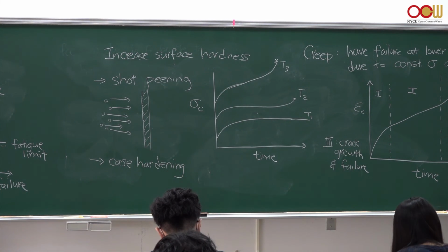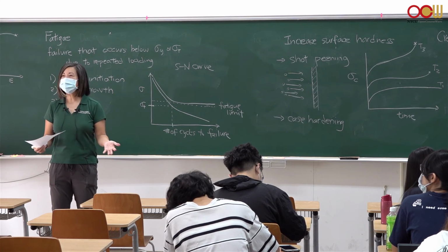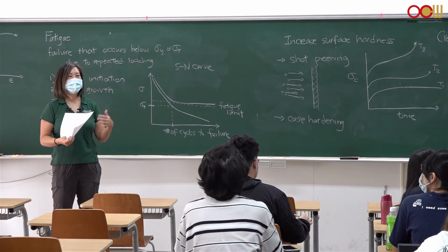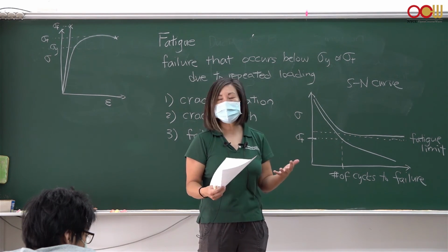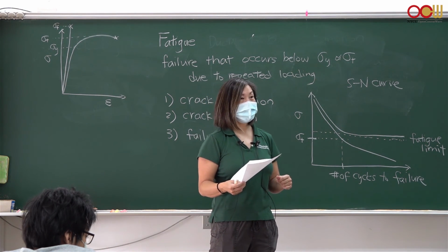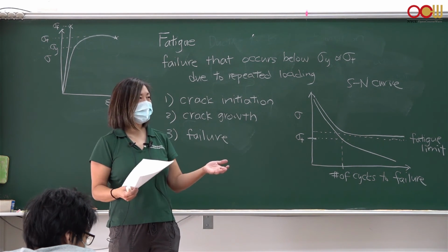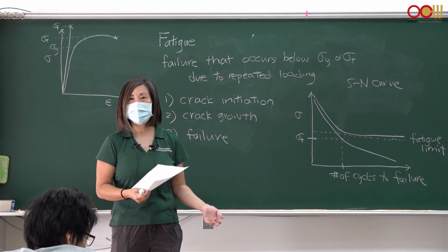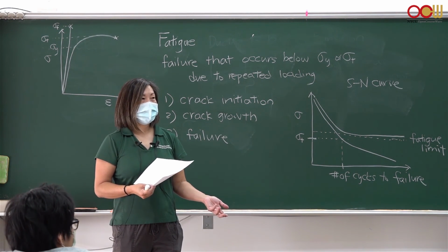So why does creep happen? It's actually quite complicated. It is increase in dislocations. It will have eventually cracks that form, propagate. But in every material, the dislocation increase happens a little bit differently. So it really is not something that can be easily predicted. You basically have to do experiments. You take a material, put it under a load, and then at an elevated temperature to see how long it will take for that material to have significant strain. And so sometimes it might take too long.